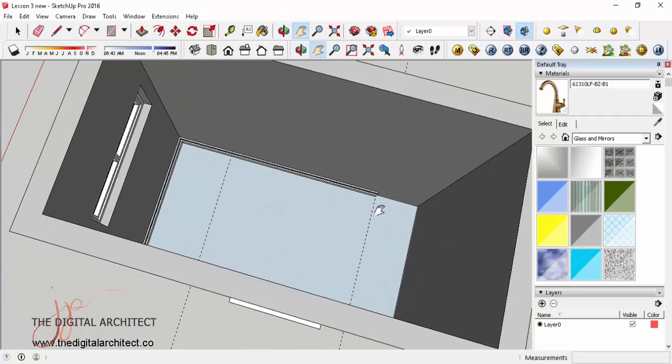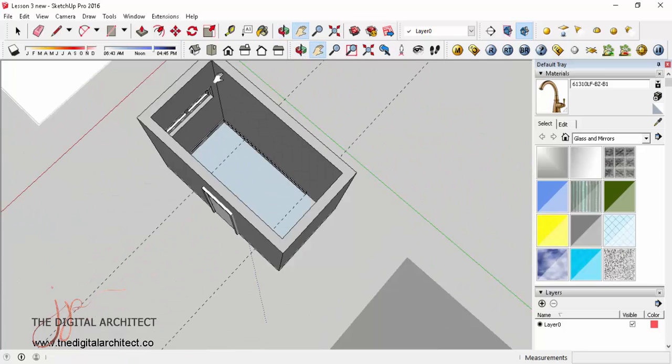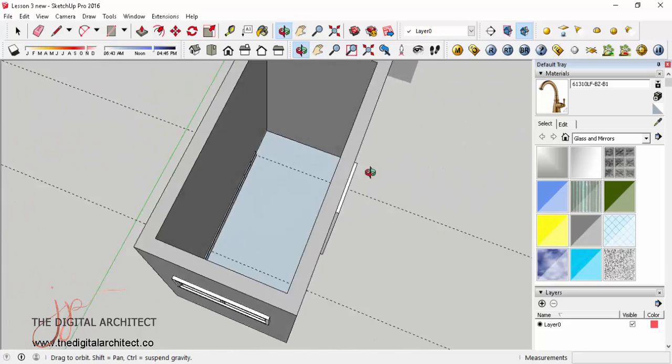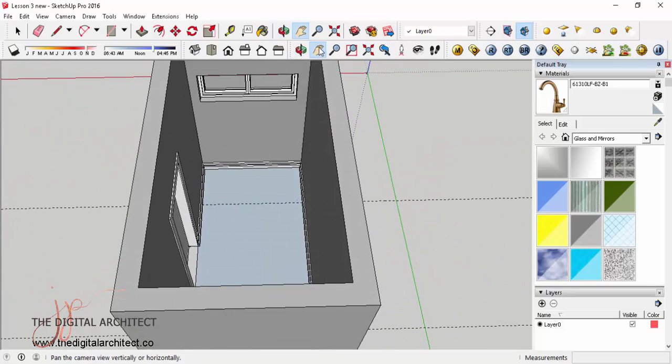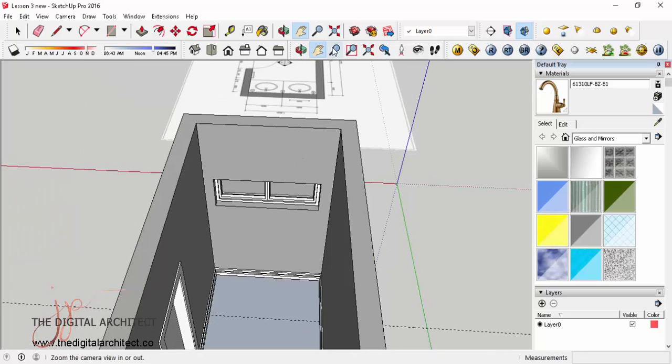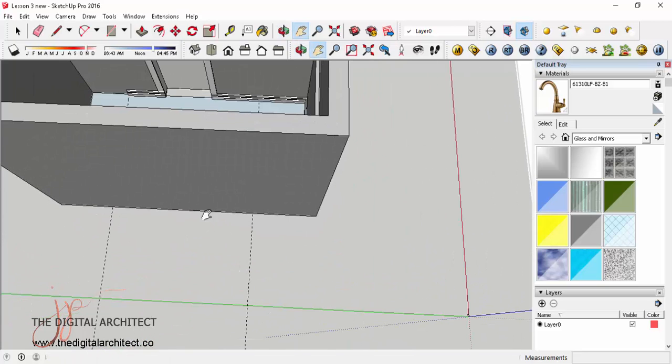So now we have the skirting there, and of course if we have a skirting down there, we should also have a molding or a trim up here, just to make it a little nicer. So how about let's do another trim at the top. Just how we did the skirting for the floor, let's do the molding for the top by creating a surface, which is let's say 100. So just select rectangle, 100, comma, another 100. There you go, you have a rectangle there.